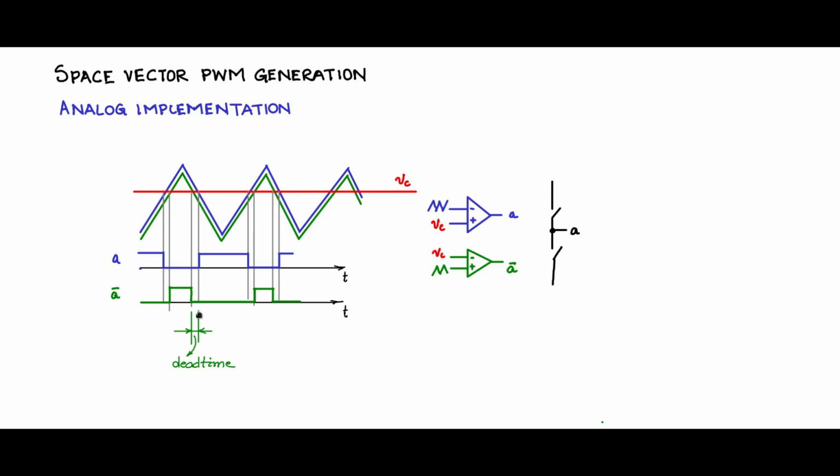You include the dead time in the analog case by introducing a small offset between two carriers of the same frequency, whereas in the discrete case, you include this dead time by having a small low bit count counter and introduce this dead time by adjusting the count value of that. This would in principle be the way it is implemented in analog. There is one more small item that you need to include, which is injecting third harmonic, triplen harmonic. Why and how, I will tell that.